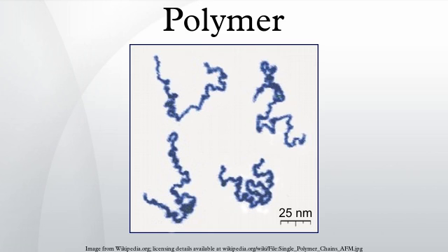Because polymer chains are so long, these interchain forces are amplified far beyond the attractions between conventional molecules. Different side groups on the polymer can lend the polymer to ionic bonding or hydrogen bonding between its own chains. These stronger forces typically result in higher tensile strength and higher crystalline melting points. The intermolecular forces in polymers can be affected by dipoles in the monomer units.